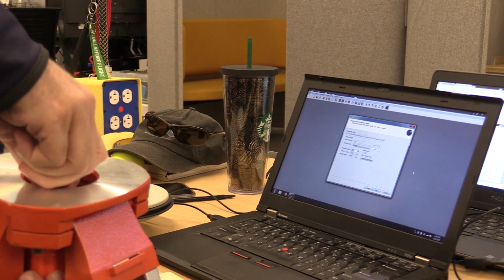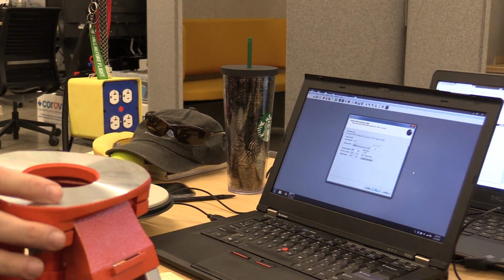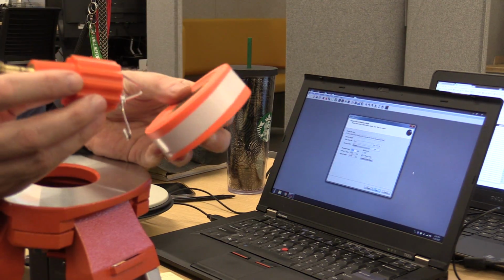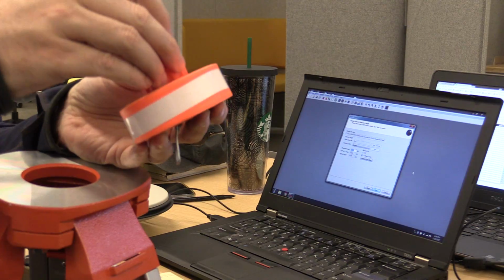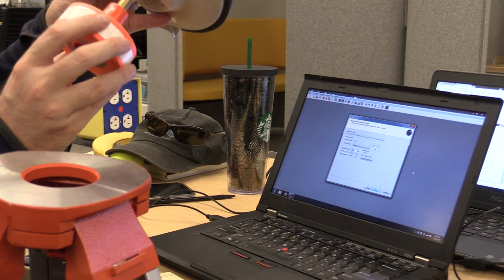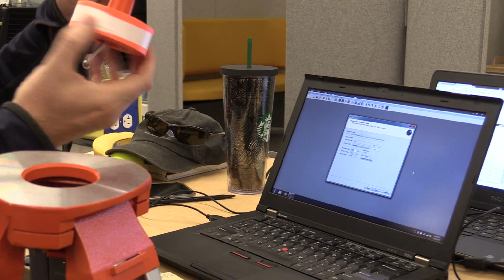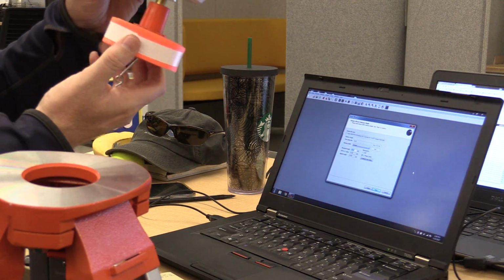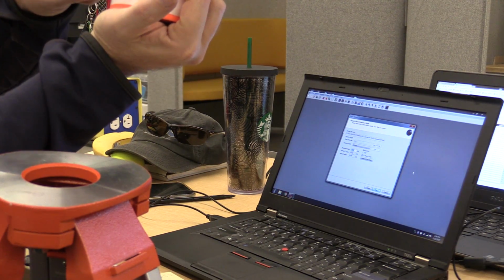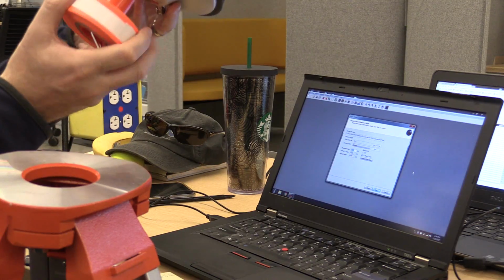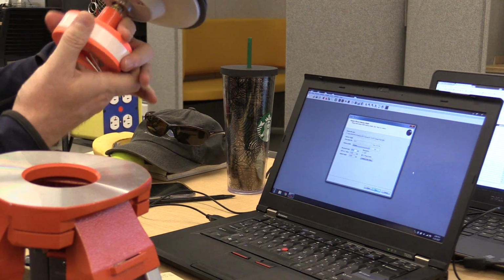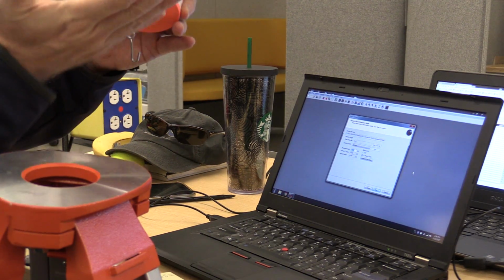And he just used some construction tape to actually make this work. So he took this construction tape, put the pin in, and when he screwed this into the antenna and set this down on the ground, he marked where the reference plane is. If you look at that, he marked on there, it's 72 millimeters from the ground. Now, this little hook was not on there at the time we took that off, so it sat flush.